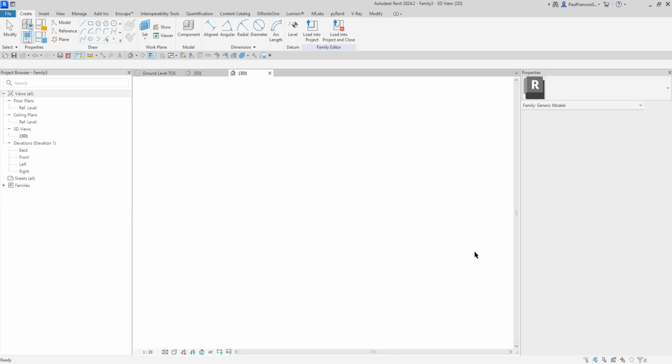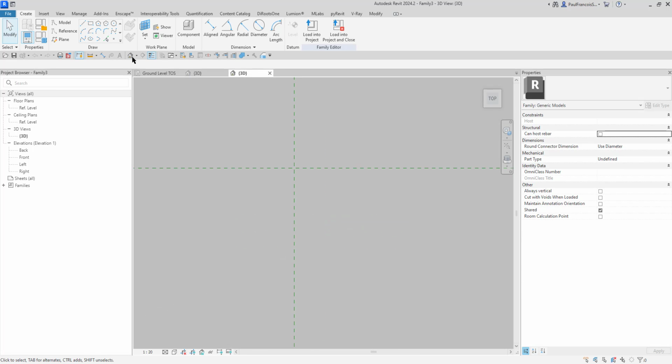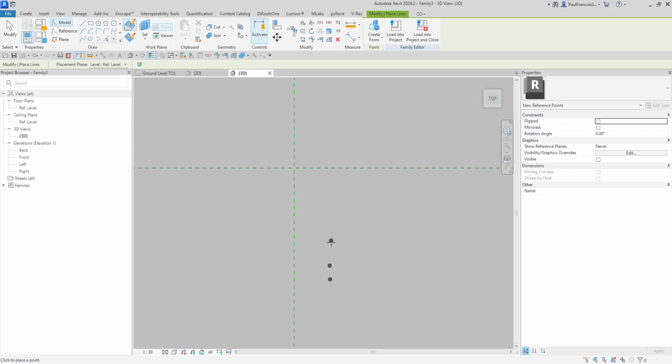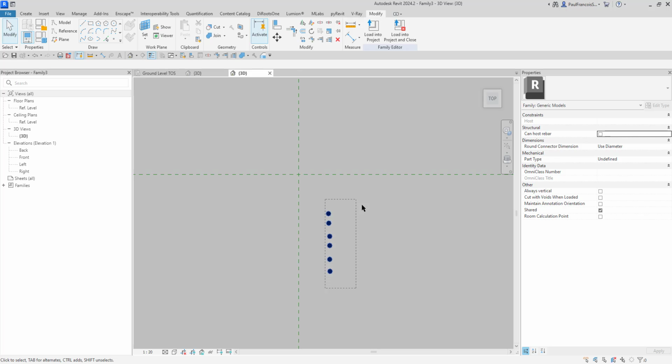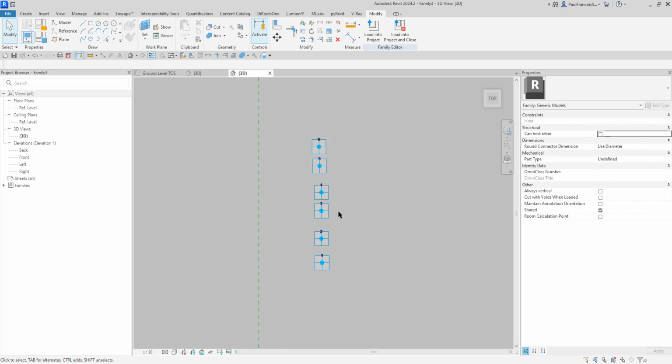And now we have to create a bunch of points. Now this is dependent on how long the cable is and how many curve points there are and so on. You could go overboard, but remember, for every point that you place, you have to place it within your project as well. So again, it's not critical exactly where you place them, you just need to place them in sequence. So there's 1, 2, 3, 4, 5, 6. Okay. And if you change them into adaptive points again, you can see how it's points number 1, 2, 3, 4, 5, 6.